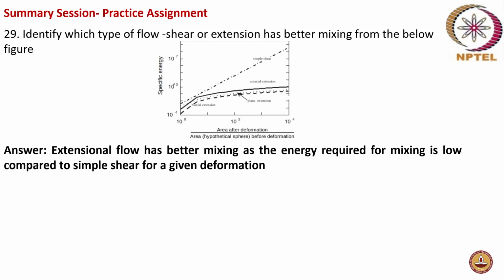It is actually extension flow that has better mixing, because in extension flow you can see that the specific energy required for the deformation to happen is lesser, right? Yes. Whereas in simple shear it continuously requires a lot of energy, more energy compared to extension. Okay. Hope Paul, you also got this point.